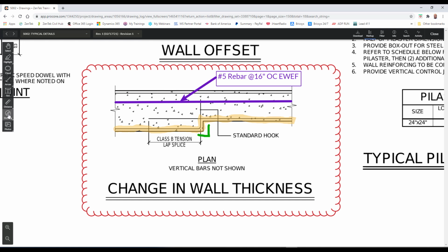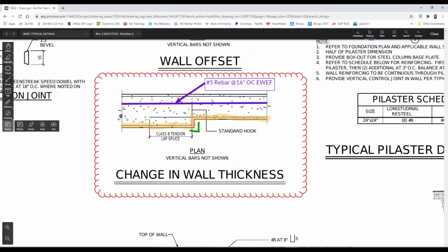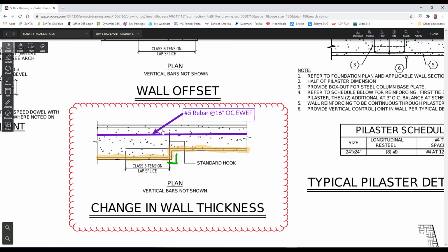show you that there are more advanced tools here, that I can create links to other drawings in my drawing set, right? I can even go in, I can add photos, and I can create links to any of my predefined Procore structures. So if I have punch list items, construction issues, right, or observations that I've already defined in my project, I can just click on them and put pins to any of those on any of these documents in these drawings. Now, I can zoom in and out as I need to. I can select, right, individual items. I can do mass selects, you know, whatever I need to do to select and modify and adjust these.